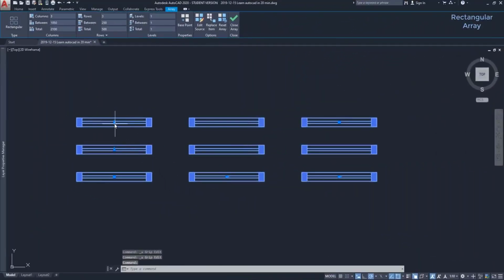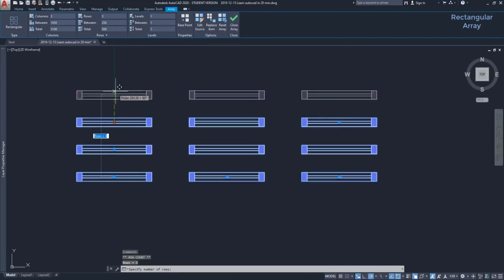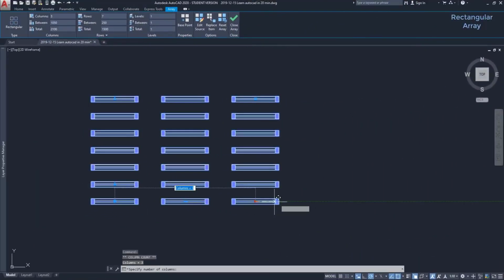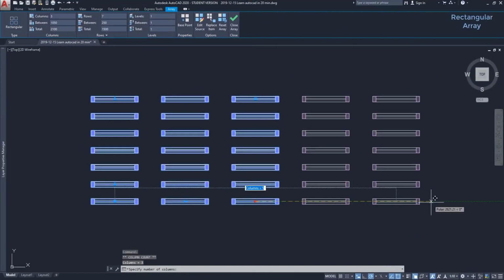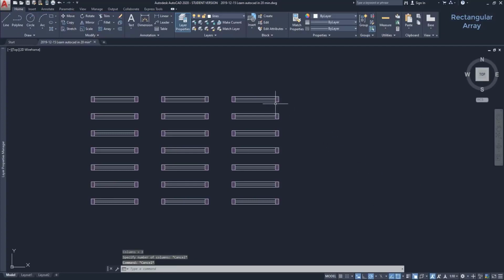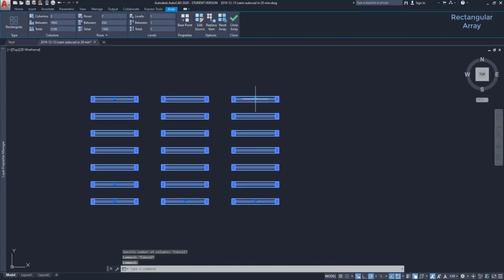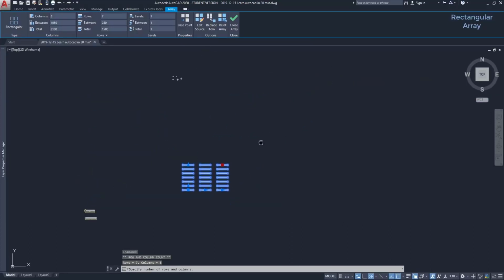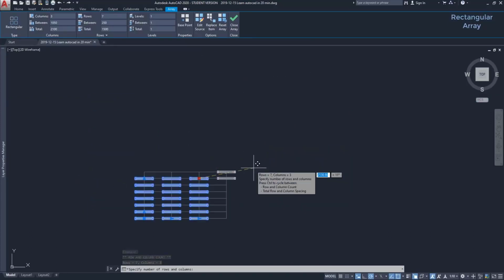If I click on the grip at the last row, I can add more, for example, 7. If I click on this side, it's the numbering of columns that I can change. The grip on the opposite corner changes both rows or columns by dragging the mouse. Basically, these operations can also be performed on the Array tab, but sometimes it's just more practical with these buttons.